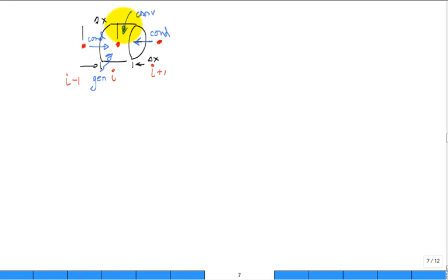I personally think about the node that's the focus. I'm doing an energy balance for node i; it is cold, lower temperature compared to all the other nodes around it. So if that's true, then what is my conduction going in from node i minus 1? Well, it'll be temperature T(i minus 1) minus Ti. That's my driving temperature difference. And because Ti is lower, I want a positive delta T to drive it in.